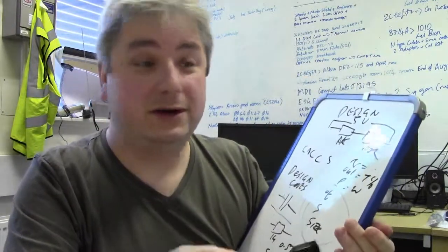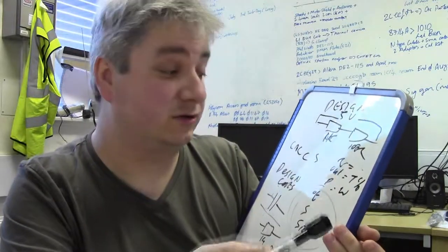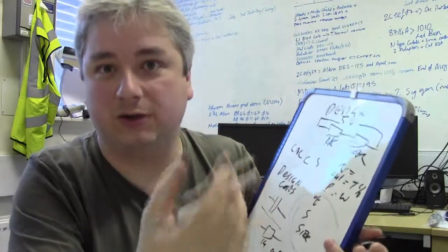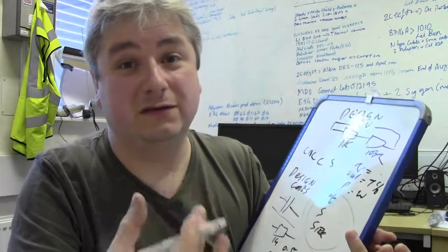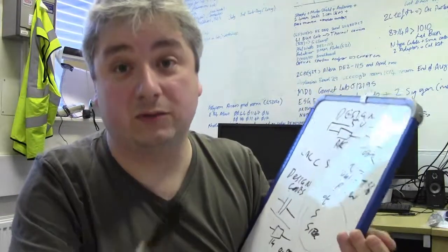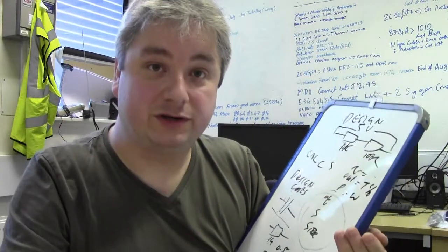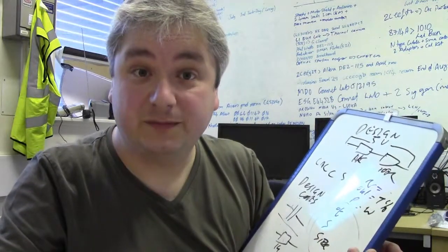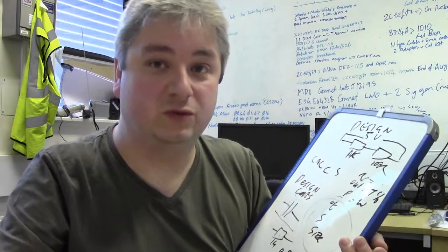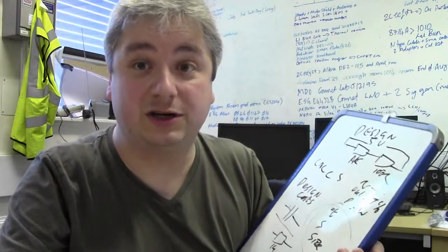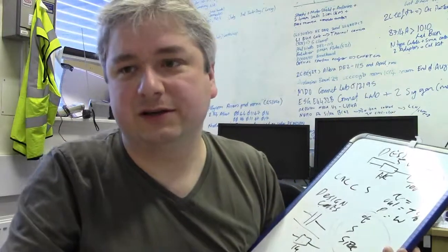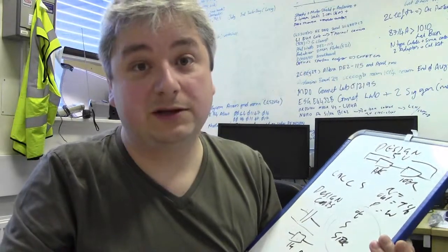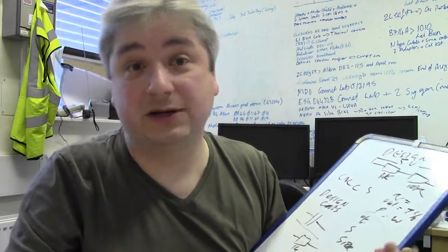It's all about picking and choosing, and sometimes in your design constraints, because you're so constrained, or your design is so open, you've got a huge choice or a very, very small choice. And sometimes you do have to make compromises. Sometimes you might have to use a resistor with a super huge wattage, but it's really, really cheap, compared to a component which has got a very small wattage, which is really, really expensive because it's been more highly engineered. It might be a current sense resistor, very, very small resistance, but it has to withstand high wattages, depending on what situation you're in.